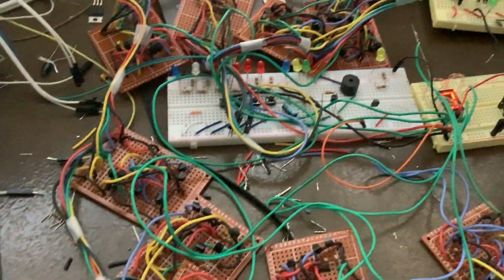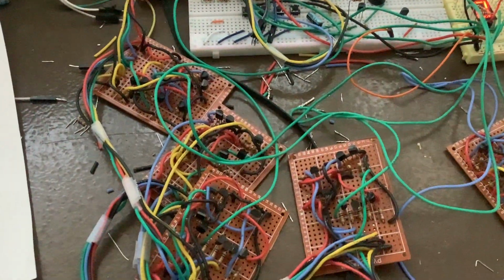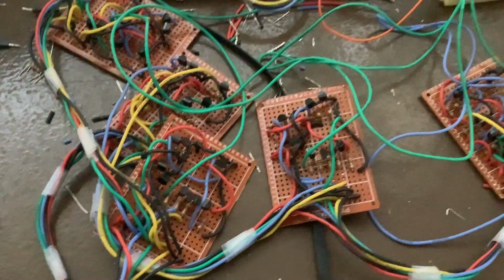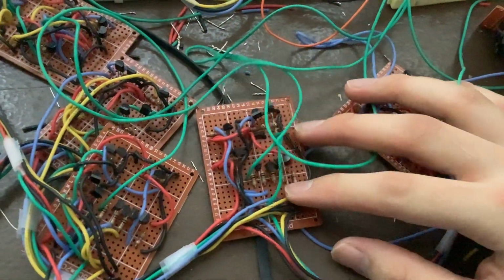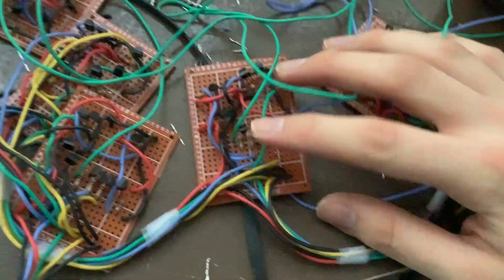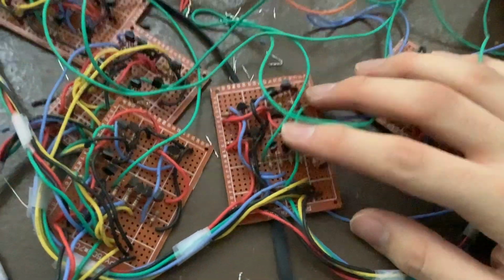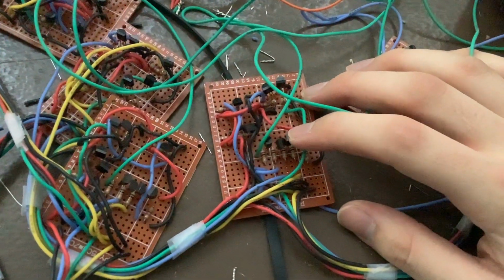You could see, oh, there's a lot of circuits right here. Well, they're actually not very complex. It took a long time to make this, but I'm really only using 3 types of gates. There's OR gates. You can see this is a 4-input OR gate, which is basically just 4 transistors in parallel.